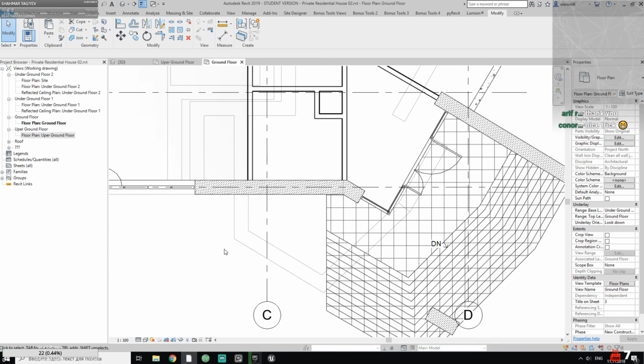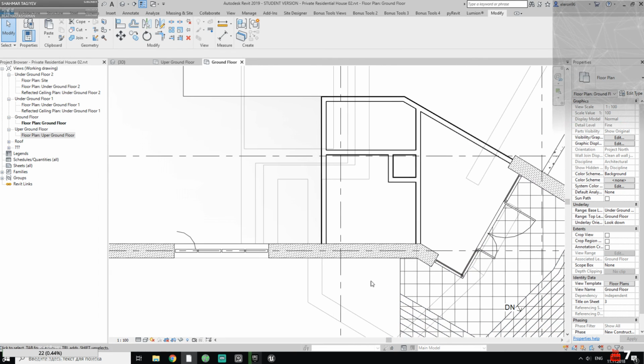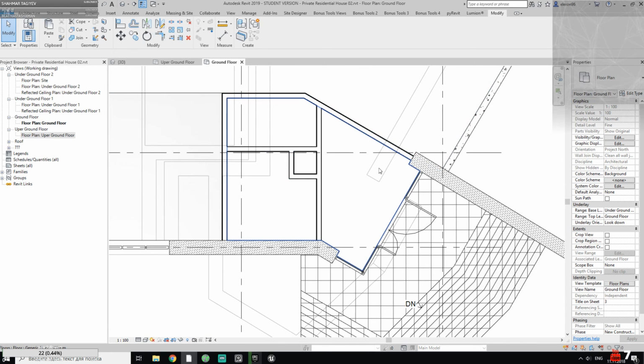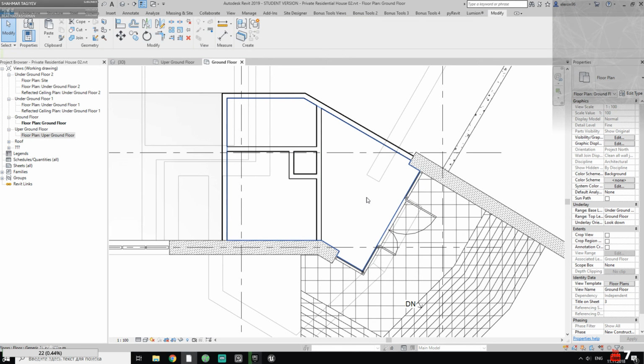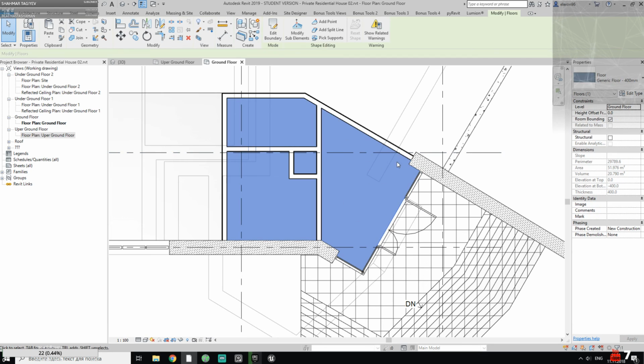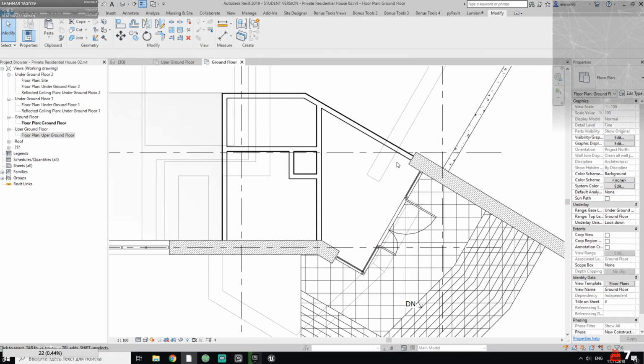Yeah, but you know most people don't really know how to work this panel. I'm not kidding. For example, now I am able to select my floor, right? But some people call me and say, Nico, please, can you help me? I cannot select my wall, because they have switched off select elements by face, and of course they cannot select this floor because of the face of the floor here. Of course you can make the corner if you target it, like this, but most people don't know that.